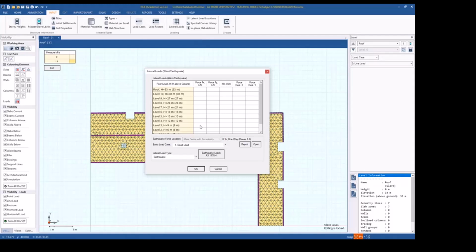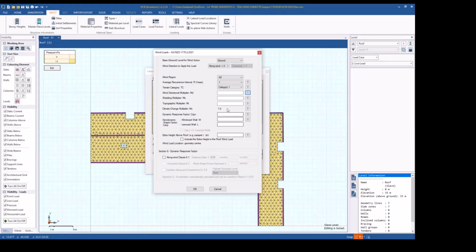Click on lateral loads. Don't worry about dead load and live loads. North wind, click here. And we do have this handy tool, where you're going to be asking the software to adopt the standard. So select here and just put in the options we used in Structural Toolkit. I will leave that to you as well. There were a couple of multipliers. I can tell you in your case, all those were 1. Take them as all 1.